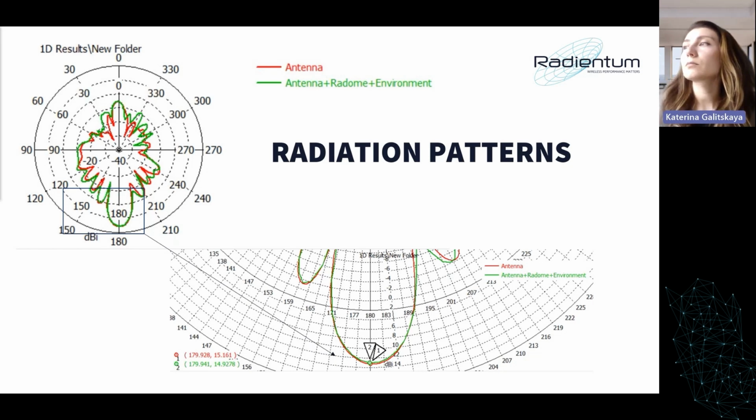For example, when you want to take into account the thickness of the radome. So you already have your millimeter wave antenna simulated, and then you just change, for example, you have a parameter sweep on the thickness of the dielectric of your radome or epsilon, and you don't need to resimulate the antenna, because it already has fields from the previous simulation that you've done with the hybrid solver.